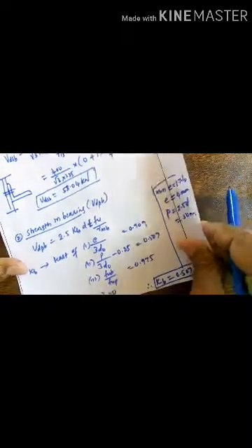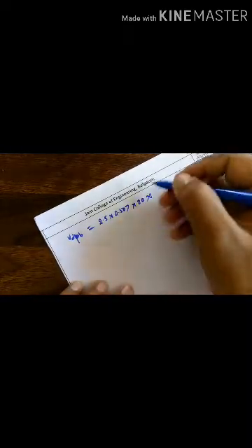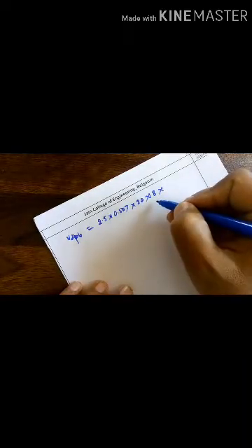After this, substitute all the values in VDPB. You will get VDPB as 2.5 into 0.507 kb value into 20 into thickness 8. Why thickness 8? It is the least value of gusset and angle.